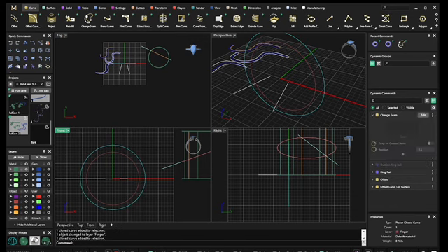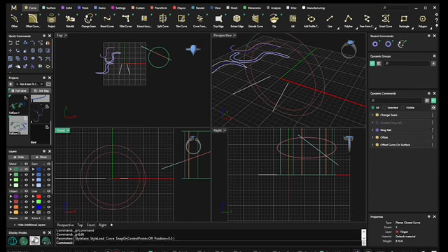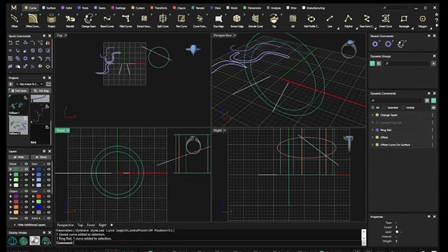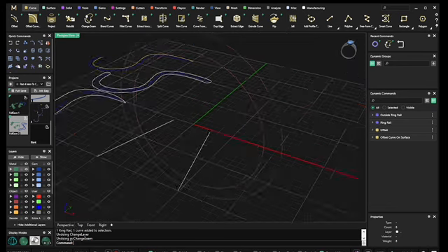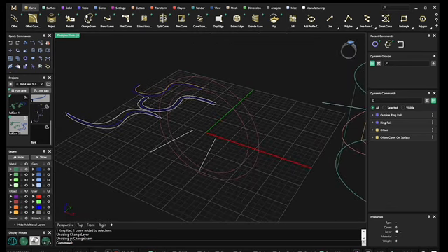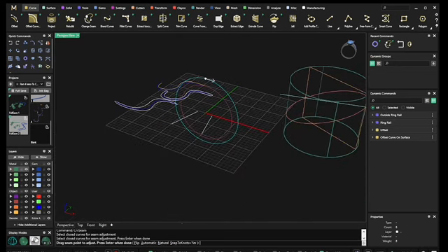Let's find out what it says here. Edit, snap on control point, position, change seam. All right, very basic. I'm not sure if it's the same thing, so let's back up because I want to show you what I usually do. So type in curve, CRV, seam. If you forget, you can type in seam and then it'll pop up. And then I select this one and I press enter and I adjust it.